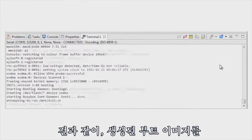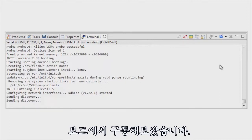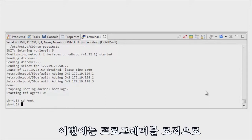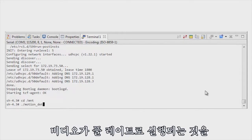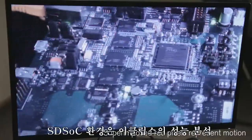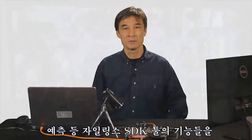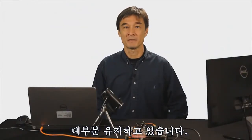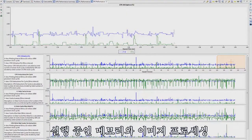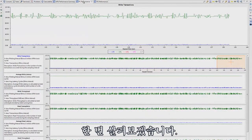We copied the generated boot image onto the SD card, inserted it into the ZC702, and powered on the board. After Linux boots, we run the application, this time with programmable logic accelerators, and see that the video now runs at full rate. The SDSoC environment inherits many capabilities from Xilinx's SDK tools, including a performance analysis perspective. As our application continues to run, let's take a quick look at the traffic between memory and the image processing pipeline running in the Zynq programmable logic fabric.